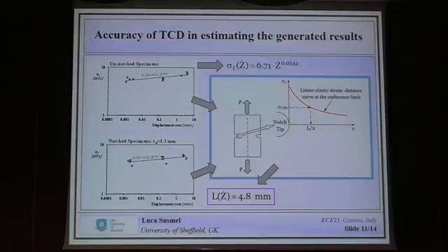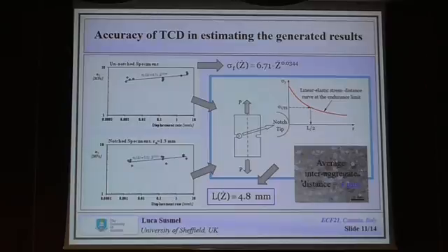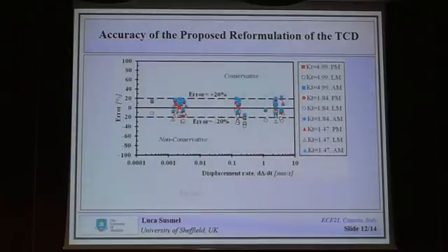So we are in the finite fracture idea. That is, the crack initiates at the stone, it propagates through the matrix. As soon as the length is equal to about the average interaggregate distance, the specimen is gone. So this was the structure, and this is the accuracy of the approach. As you can see, we got very good results using both the point method and the area method.